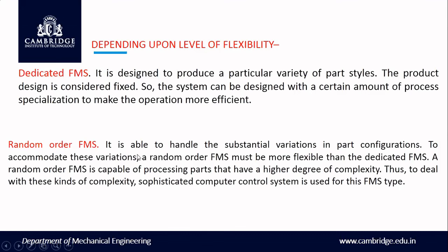Now the random order FMS. It has the ability to handle substantial variation in part configuration. Here a number of part configurations can be varied. In the dedicated one, the product design is considered fixed, but it is designed to produce a particular variety of the product. That is one particular variety you can do. That is the dedicated flexible manufacturing system.